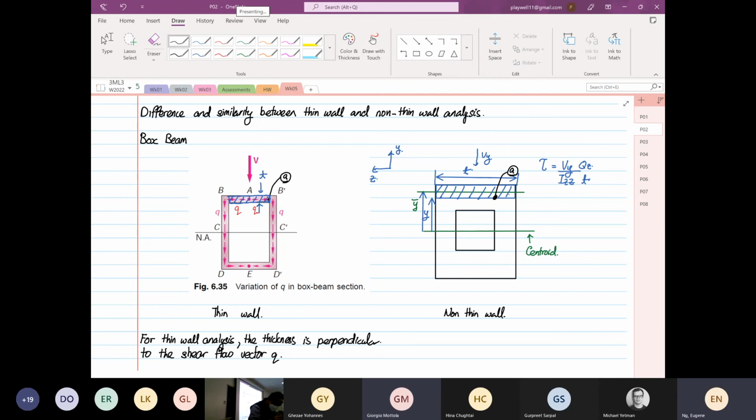Okay. So the shear stress now is equal. So the shear stress tau is equal to VQ over I, always constant. So the rules that we have written before still work. I repeat again, the rules that we have written, remember we have written 5 rules, still apply. The Q, for this case, is different because thin wall.